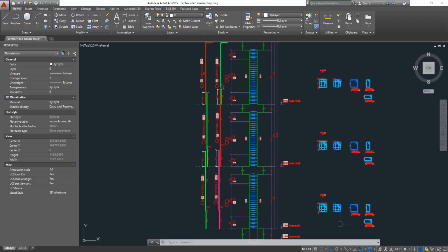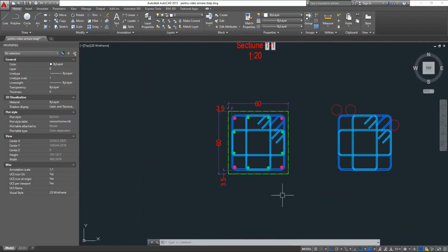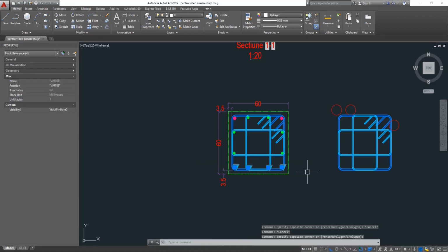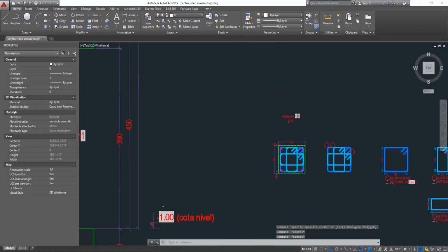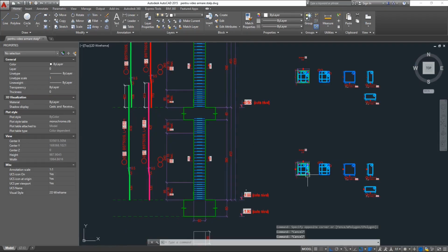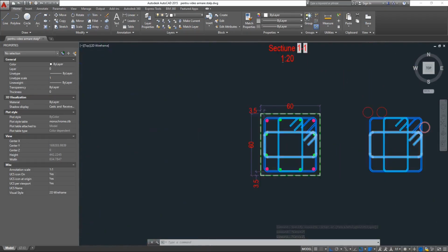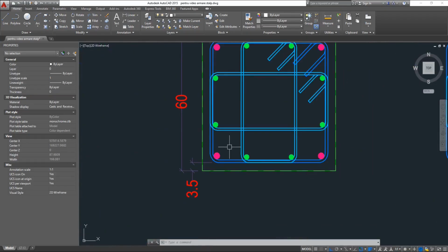So we make the assumption we're going to watch the column on each level from the bottom of the section upwards, and basically we're going to see only this set of rebars on the elevation. So we're going to choose sets of rebars according to the diameter.